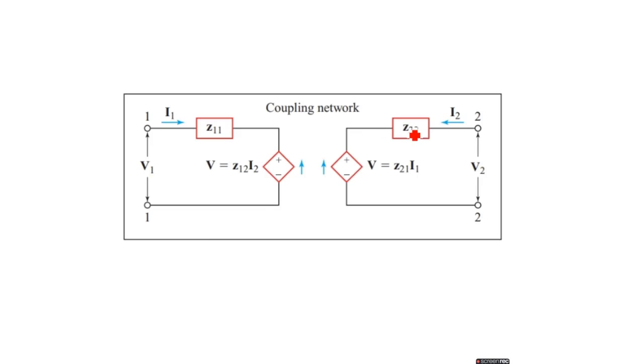So that is the equivalent circuit of a two-port network. You should keep that in your mind. It is port 1, which has 2 terminals, and port 2, which has 2 terminals, total 4 terminals. This is the equivalent circuit of the given network in terms of Z parameters.